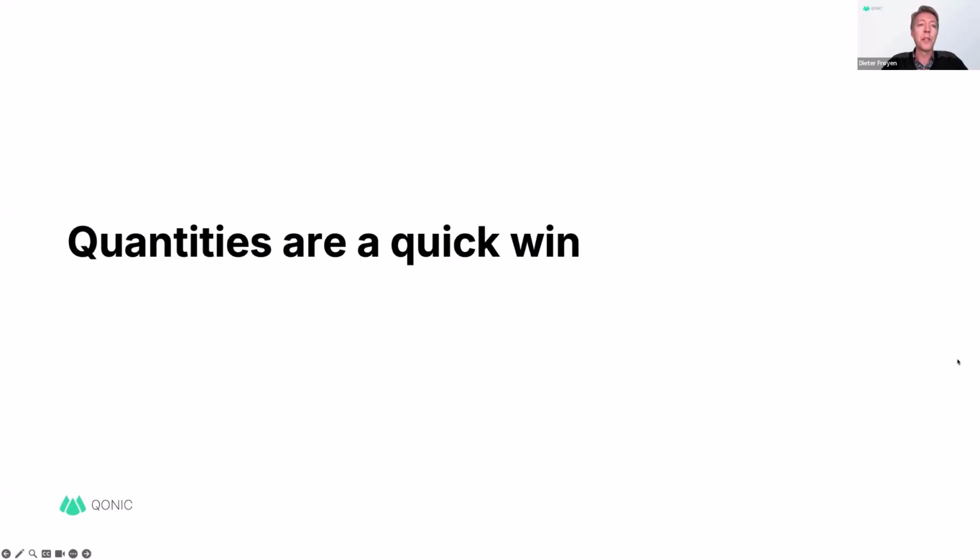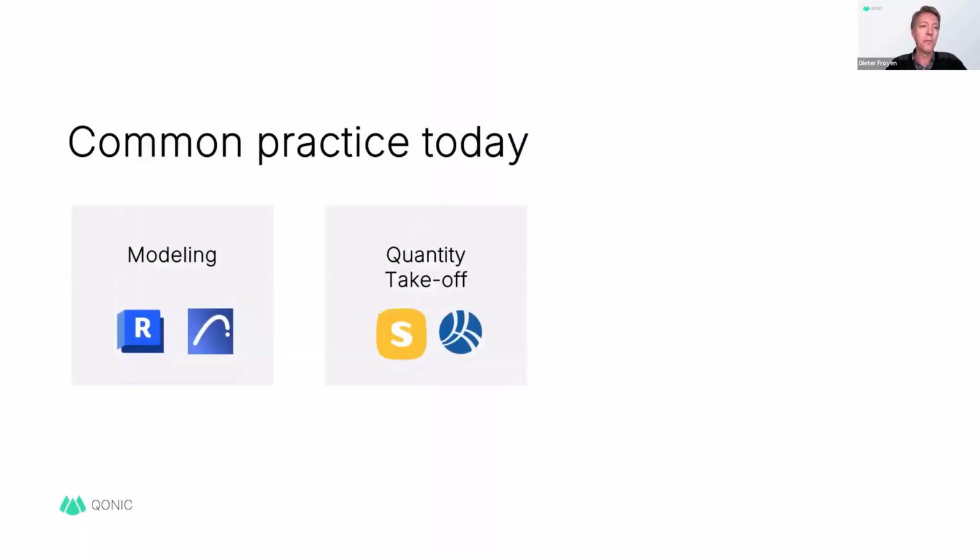I'll start with the quote, "Quantities are a quick win." Of course, you can do a BIM project without quantities derived from the BIM model, but when you take time to invest a little bit more time so that your BIM model is useful for quantity takeoff, then you'll gain a lot of time afterwards for yourself and for all the team members. And your quantity takeoff will be less error prone. There is a but. You can encounter some hurdles before you have a useful and correct quantity takeoff. Well, let's dive into that more in detail.